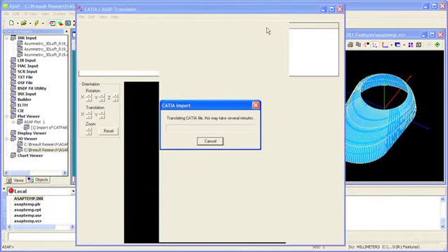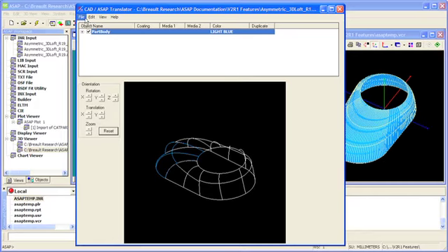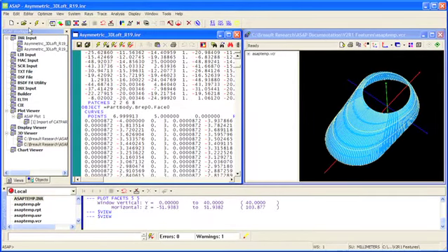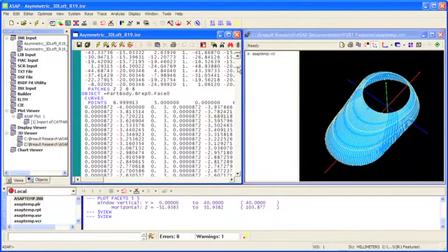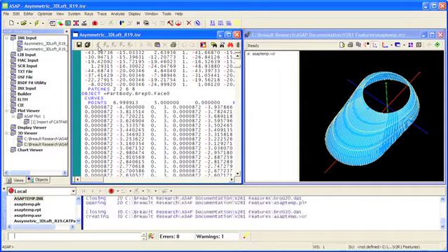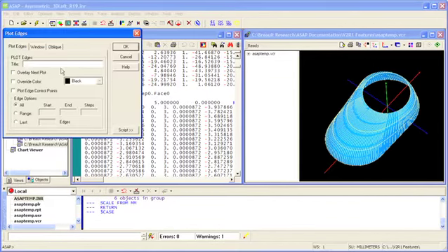So we'll click OK, and we will again finish the translation process. Now we note that in this INR file, we again have a series of curves that have been constructed into a set of second order Bézier patches. And we'll run this file, and we'll render the surface exactly as we did previously.